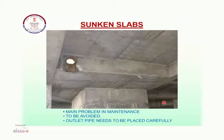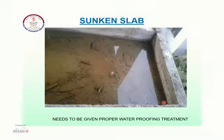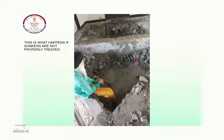Sunken slabs are very important. We must give proper treatment, proper testing and proper arrangement of spouts. The position of the spout is very important, otherwise this is the building. I have seen that a lot of water has gone inside the sunken slab and throughout the year it drips. So, you can imagine what will be the condition of the rainfall inside and what will be the life of the building.